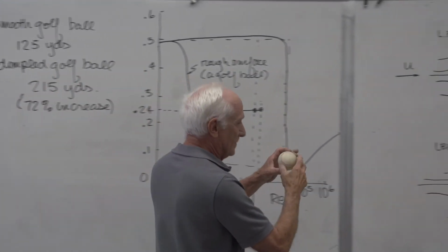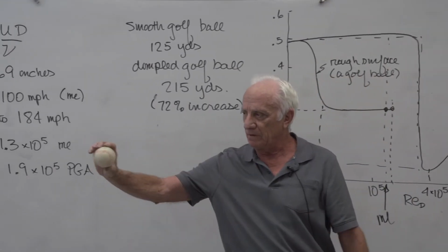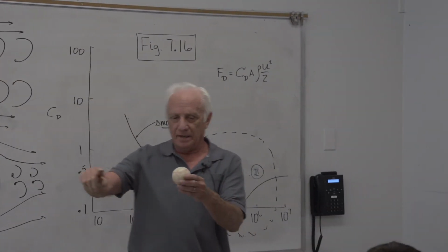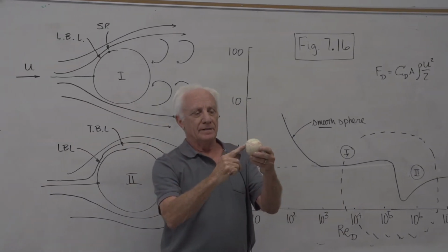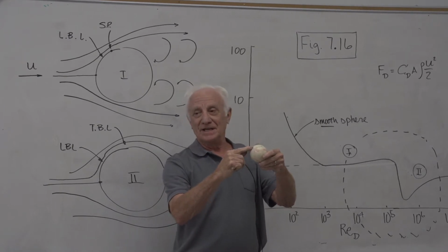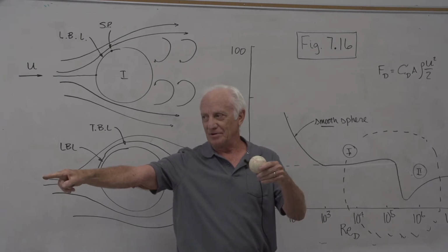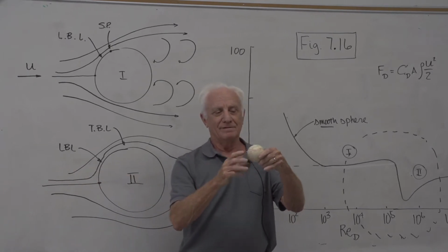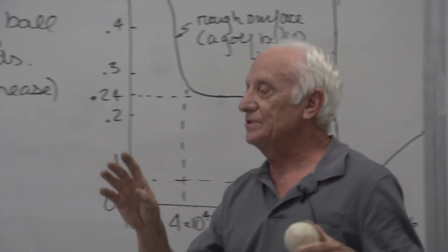So here comes the baseball. Let's assume it doesn't move. Comes in just like that. Okay? Air hits the front. Laminar boundary layer. Hits the seams. Uh-oh. Roughness, like the table, with the boundary layer on the table. Goes turbulent. Okay. The key to throwing a good knuckleball, you can see it on TV.